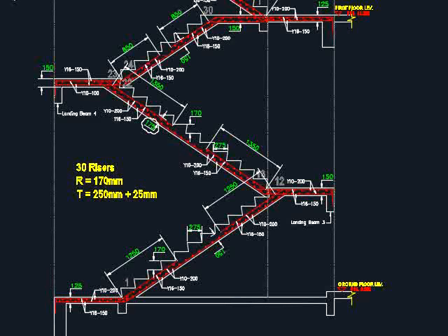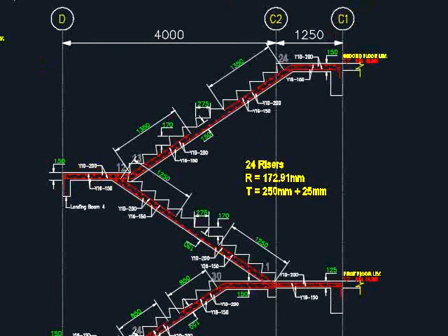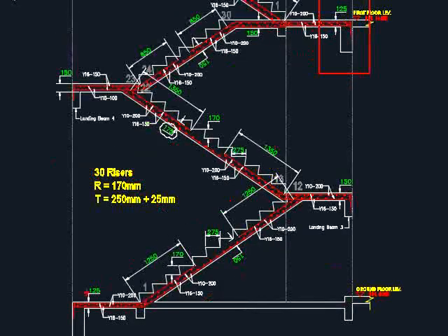And then, by the time that you are producing the detailings for the staircase, most likely your key plan has already been established. Check the positions of the staircase in accordance to the grid line. Identify the size of the beams where the staircase is going to meet at different floors. Draw the incoming beam in the appropriate size.